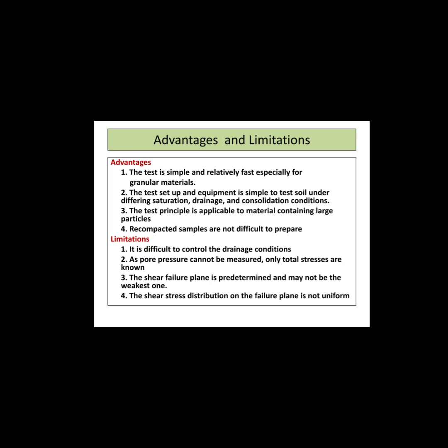of the sample. And the limitations are it is difficult to control the drainage conditions. As the pore water pressure cannot be measured, only total stresses are known. The shear failure plane is predetermined and may not be the weakest one. The shear stress distribution on the failure plane is not uniform.